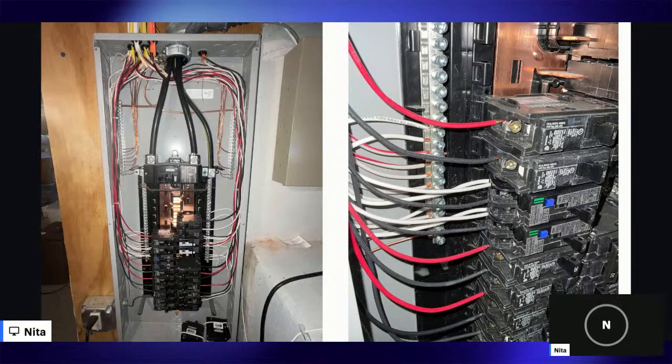My cable assembly will continue right here. This is where we see it. This is where we pick it up inside. I got my 2 hots connected here to a lug. 1, 2 connected to the lug. Boom. I've energized this bus bar. Notice this is copper. What do we say about copper? It is very conductive. So now this is energized, or hot, or power. I've got my neutral that connects here to my neutral bus bar.